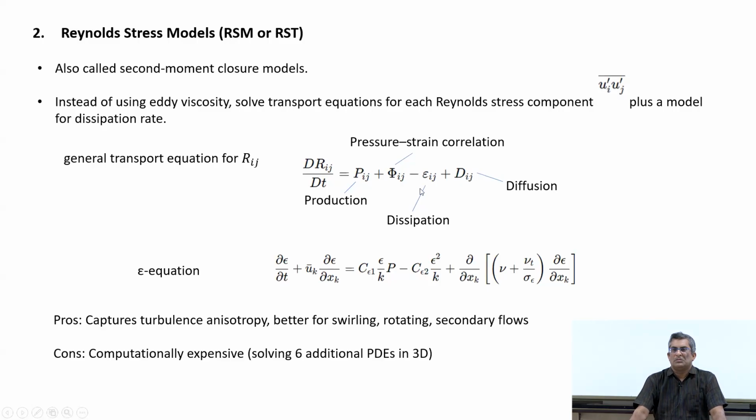So this approach obviously works better compared to the eddy viscosity model, because here you are solving the transport equations for the stress tensor component itself. But here you have these additional equations coming into the picture, and that is why it is computationally expensive, and also convergence might be an issue.